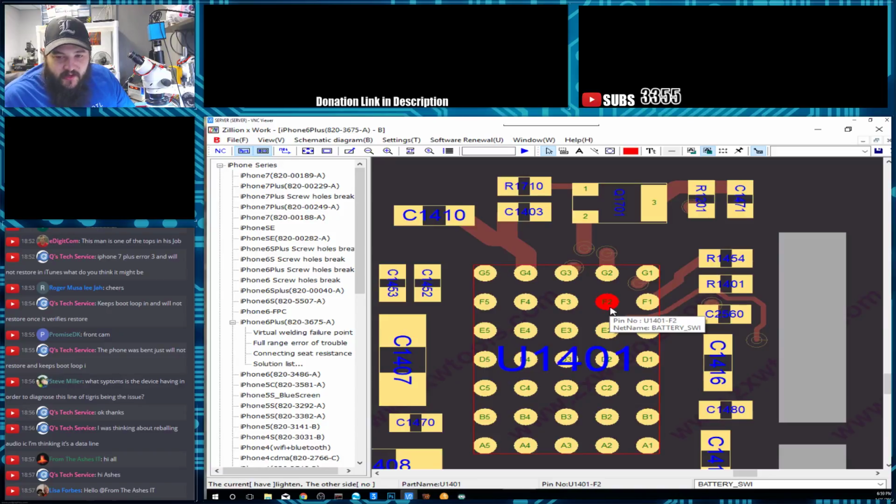It goes to a filter and a capacitor. The filter has 100 ohms resistance. I traced the line from one side of the board to the other. I even ran a jumper from the battery connector to the other side of the board to make sure that it had good connection.